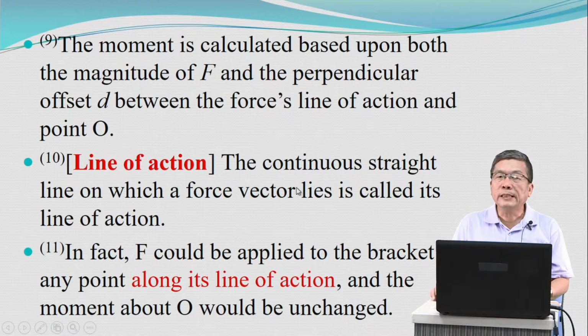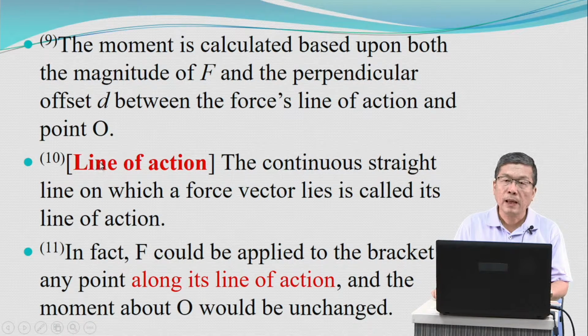The moment is calculated based upon both the magnitude of F and the perpendicular offset d between the force's line of action and the point O. Line of action.